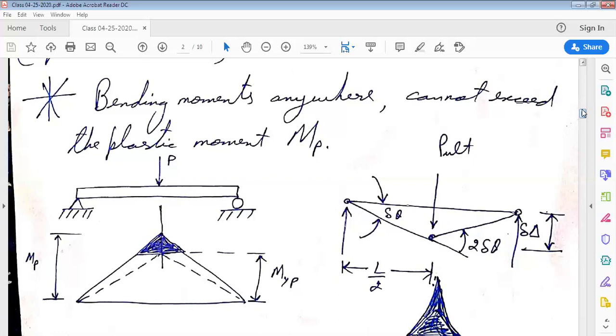Below the schematic of the simply supported beam, we have drawn the bending moment diagram. There are two bending moment diagrams, one dotted and one continuous. The dotted bending moment diagram corresponds to the yield point moment MYP, and the continuous bending moment diagram corresponds to the moment MP at the plastic limit of the structure.